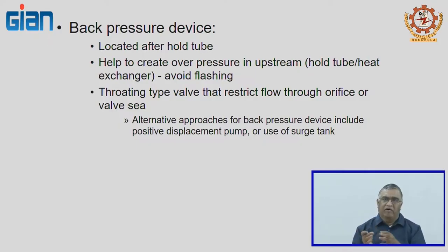With a back pressure valve, you essentially add some additional pressure to the holding tube, so that it increases the pressure within the tube. When you increase that, your liquid remains a liquid, but at a higher temperature. It may be at 130, 140 Celsius, but it flows as a liquid. If you don't have your back pressure valve, it is going to start flashing or becoming like steam, and that can create a lot of problems.